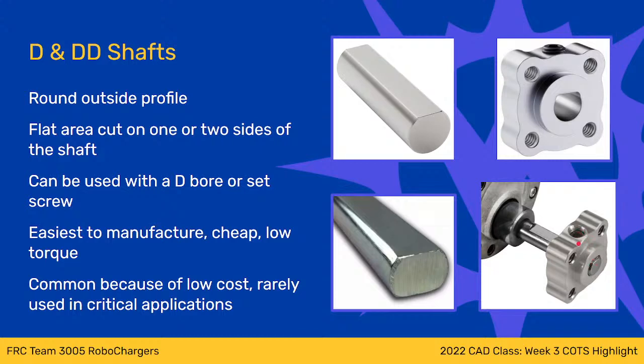You run this screw in, it screws down, and eventually it pushes on the shaft and you tighten it really tight. And basically in order for the shaft to strip out, it has to kind of bend, push that screw out of the way, which is mush the end of the screw out of the way, basically, or cut a groove through the shaft using the screw. You have to do a lot of damage to spin.